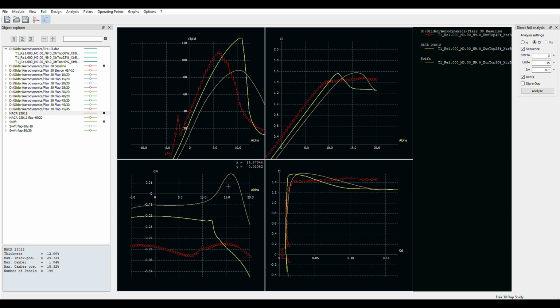Another thing I really like about the airfoil is that if you have to put in a lot of up elevator to pull the nose up, you're dumping lift and creating drag. And that's the last thing you want when you want to fly slow. I don't want to dump lift, I want more lift. And this allows me to do that because I don't have to deflect the elevon as much.